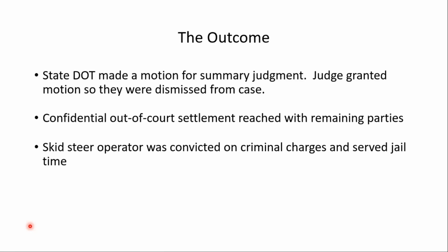And so someone alleged, well, I had forgotten that there was warning about the mowing because the signs were many miles in advance of the mowing crew. So that's something else on the mowing operation to be attentive to: as the mowing operation proceeds down the roadway, make sure the warning devices follow suit.